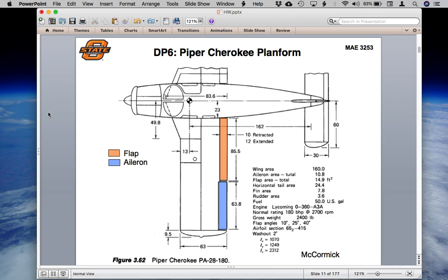You'll have to take down numbers for this because when you start to enter in the values for the wing planform, you'll need to know different station settings. So if you look along the semi-span of the wing, you'll have to not only know what the entire semi-span length is in inches, but also the geometry such as the root chord right here, as well as locations of the flaps, not only along the chord but also along the semi-span, to do a fully accurate geometry of